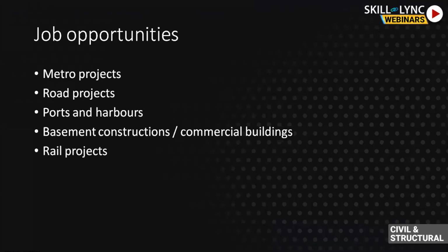Where all these walls are used is particularly in metro projects. When it comes to underground construction, diaphragm walls are used predominantly in many metro projects. Other than that, secant pile walls are also used in some cases for temporary excavation. Soldier piles and sheet piles are used for ancillary building constructions.